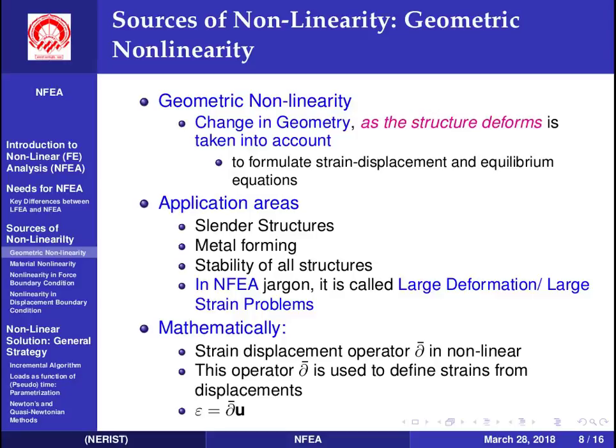And the application areas of this geometric nonlinearity are analysis of slender structures, metal forming, stability of structures. In finite element terminology, we call them large deformation or large strain problems. So mathematically describing, the strain displacement operator, which relates the strain to the displacement, is a nonlinear operator which depends on the displacement itself, and that's why it is a nonlinear problem.